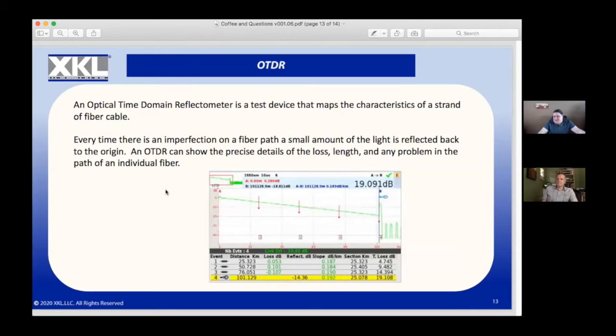The last, and this is the last technical one, is the OTDR. OTDR being just a test that's run on a piece of fiber. What this is doing is actually sending a piece of light down a dark fiber. It's a tester, and it just lets you see the optical characteristics of a piece of fiber cable. It creates a report, and you'll often hear people ask, have they got an OTDR report on the fiber link?